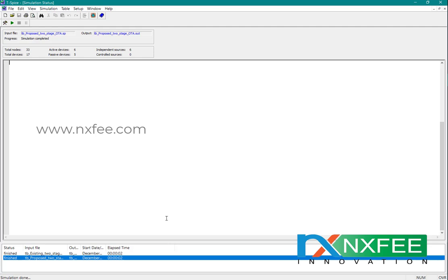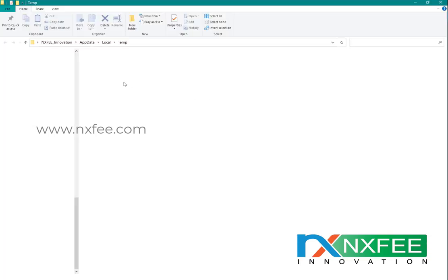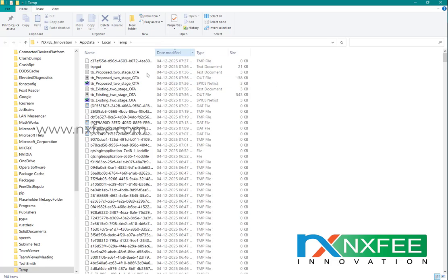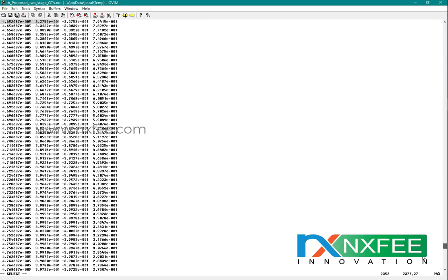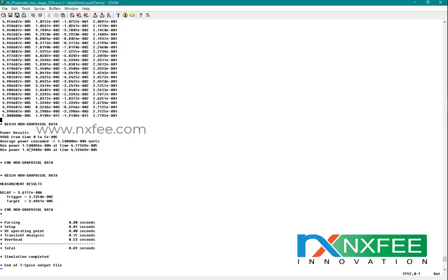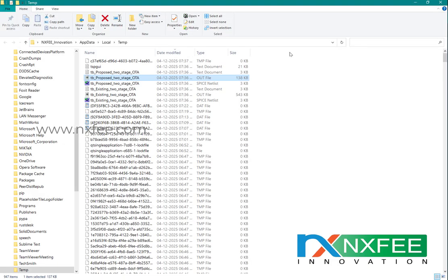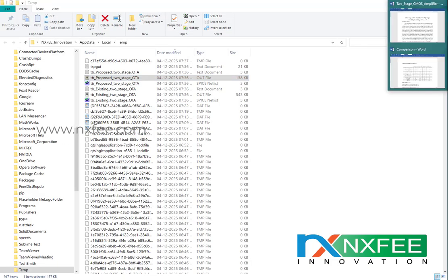The circuit analysis we have done within T-Spice. Here you can analyze the out file for the proposed design. The MOSFET count is only 6, the power consumption is 1.5e-4, and the delay is 3.6117e-6. These measurements will be updated in the comparison table.